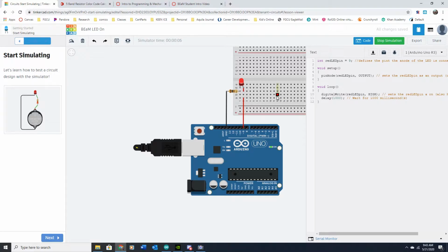One of the nice things about this Tinkercad software is that I set this resistance here to 100 ohms. And you can see what happens if I lower this down to 10 ohms or 1 ohm, we should see that the LED has a different current going through it, right? And you actually see this one here. It says the current through the LED is 52.6 milliamps, right?